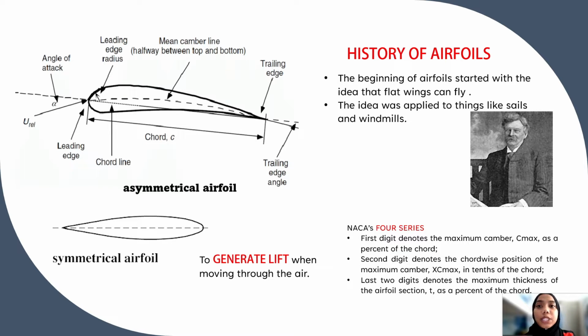As I mentioned previously, airfoils are divided into two categories, which are symmetrical and asymmetrical. These aerodynamic characteristics differ depending on the airfoil speed, weight, and purpose. Symmetrical airfoils have identical upper and lower surfaces, resulting in no lift at zero angle of attack because the chord line and mean camber line are the same. Chord refers to the distance between the leading edge and the trailing edge, and the chord line is the straight line that runs from the leading edge to the trailing edge.